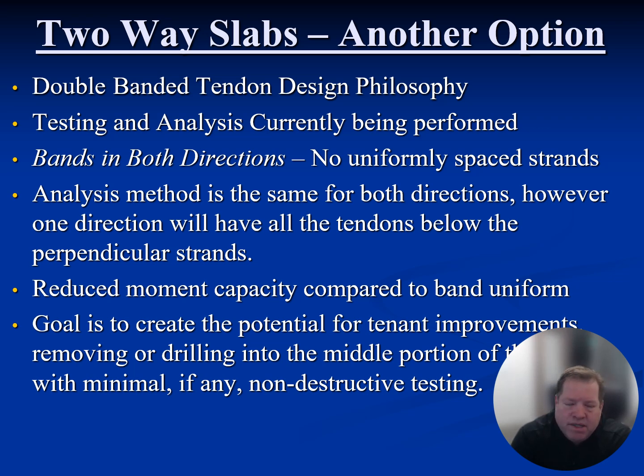One of the downsides, for lack of a better word, for PT, is that it's a rubber band. It's continuous. When you snap it at one location, you lose it anchor to anchor. And those anchors could be 200 feet long. And so if you break something in grid 7, it has an impact from grid 1 to grid 14. And obviously there's force being released, which is slightly dangerous, and people are nervous about doing that.